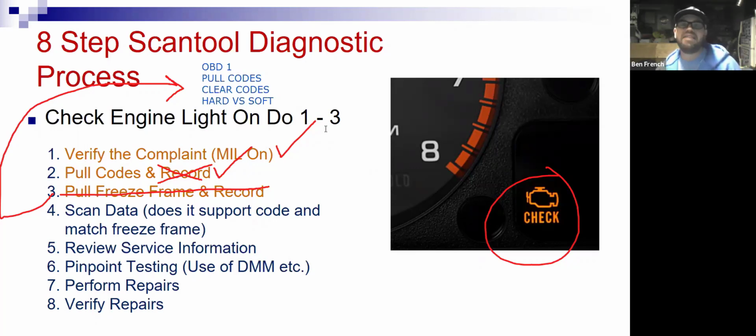The codes that came back were considered to be hard codes. And so I dealt with those first. The codes that did not come back, those were soft codes. And those could have been set by somebody's brother-in-law unplugging stuff because they're like, oh, what's this do? Those were codes you didn't worry about. That maybe there was a problem, likely there wasn't a problem, and you focused on the hard codes. That was the strategy on those cars. Remember, they didn't have monitors. The computer was checking for what they call normality. It was basically looking for circuits that were opened and shorted.